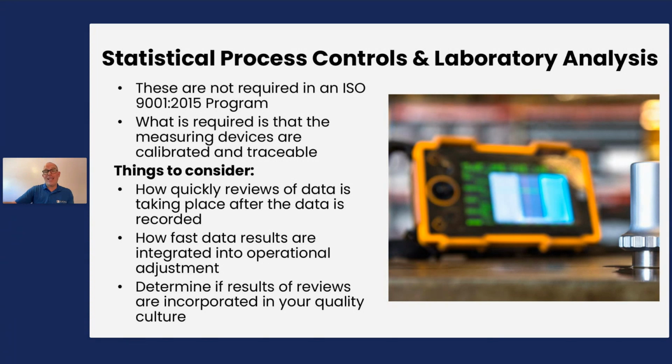And we can call that last check critical, because even though each check leading up to it is just as important as that check of functionality, if there is a problem with the board, the functionality check would be the place that would be the most representative of it. And it would require us to then go back through our process and try to understand where the error occurred. And then if it's possible to do a corrective action on that board, we would do it at that critical phase before it moves on to, let's say, final packaging.